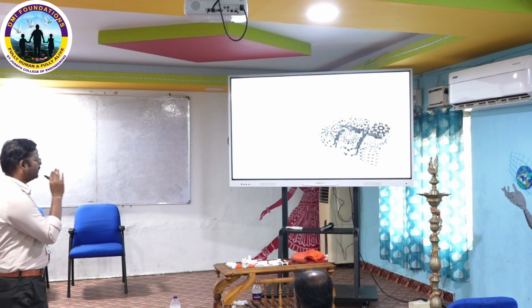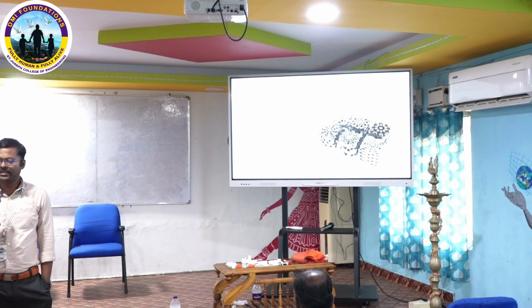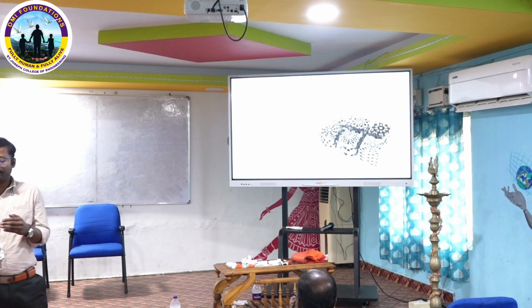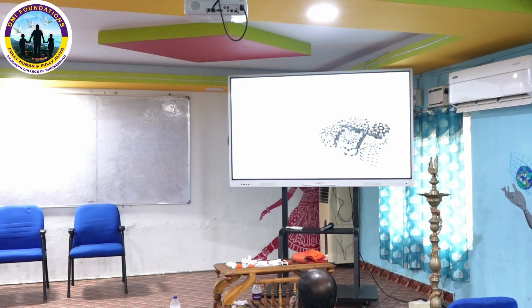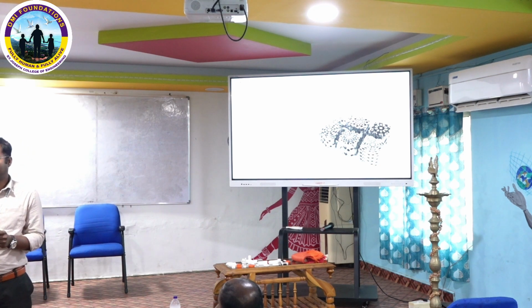Next step, what is the mechanical target? Where am I going to change it, and what is the response of the test result? For example, all of you have done tensile testing with the help of a UTM, right? Many people have done composite research. There they make a dog bone shaped tensile specimen and test it. Yes, sir. We fabricate the tensile sample and then test it with the UTM, the universal tensile machine test setup. In that we get a stress strain curve.